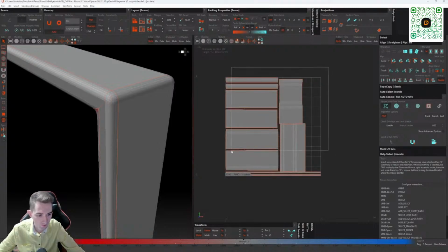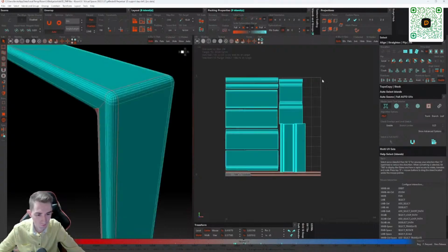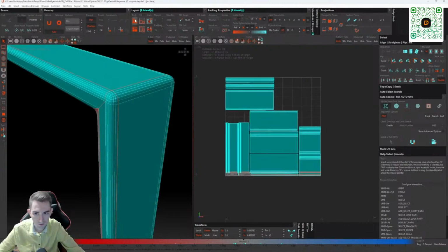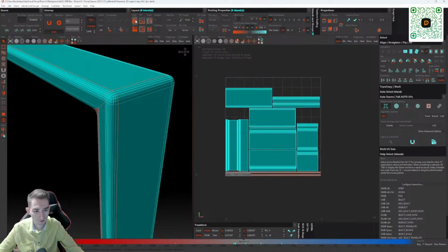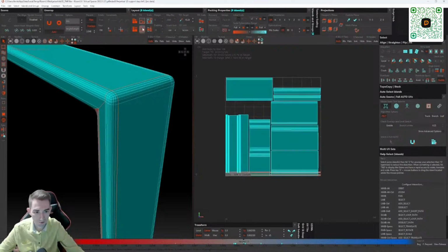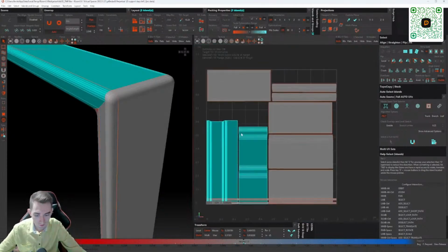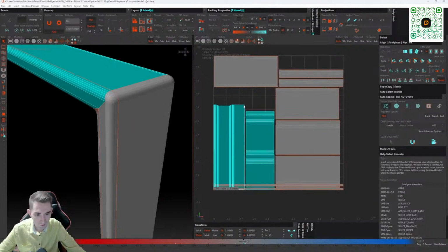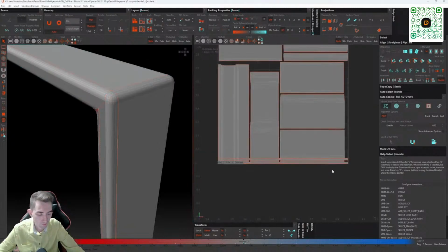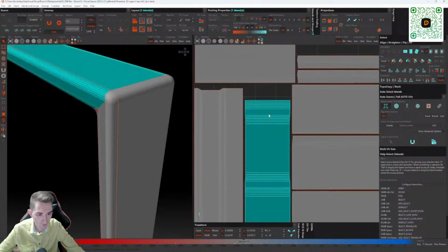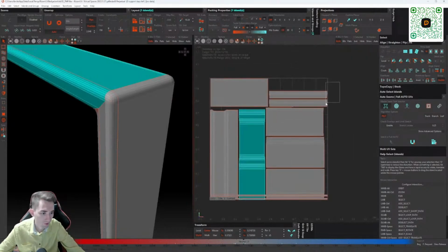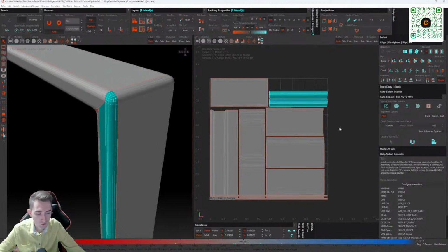So I don't like the way it packs. It's better to select these elements and pack them exactly. So it's not good either. So we'll stretch again, pack, stretch, pack, stretch. Here you can manually select the shift and the stage and tighten it up like this. In general, it is not necessary to change the proportions much, to distort, because then you may have baking problems, that is, there will be poor quality baking of light and shadows.